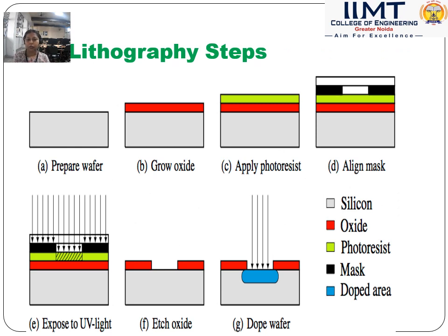And then the lithography steps can be explained with this diagram clearly. Why is lithography required and how is it applied? Because the lithography process is applied mainly for selection of doping areas over the silicon surface. As we know, in MOSFET and digital structures, there are different doping areas. We first fabricate our silicon wafer by using simple technologies.